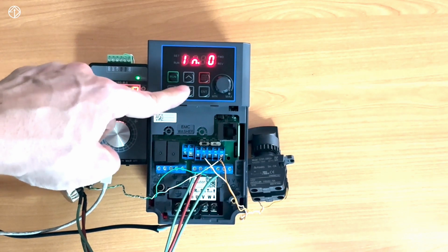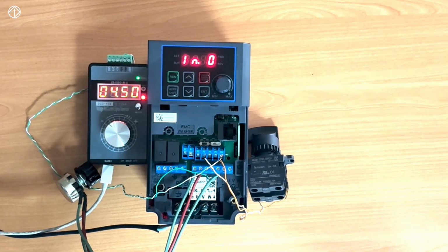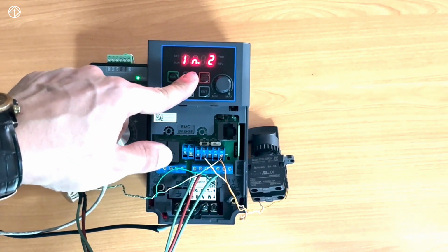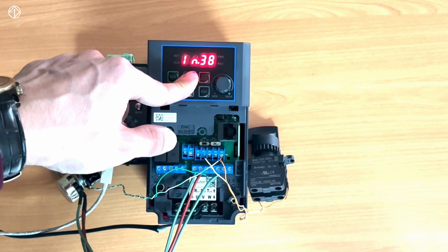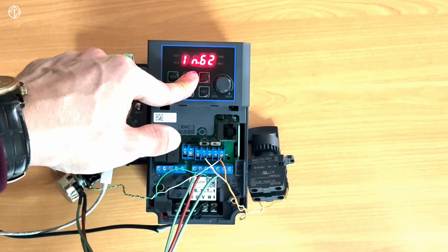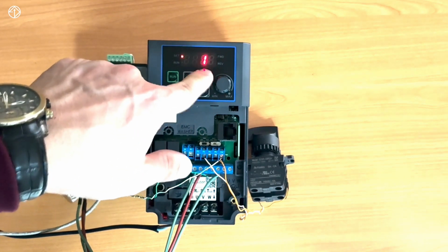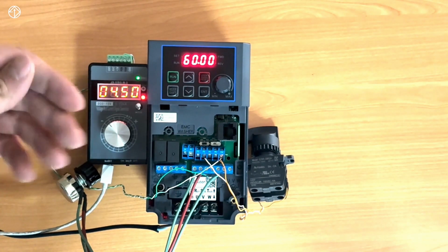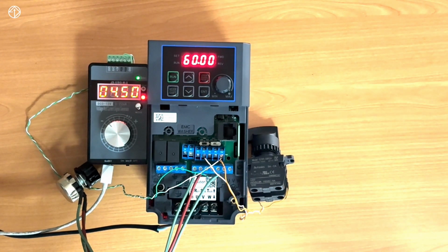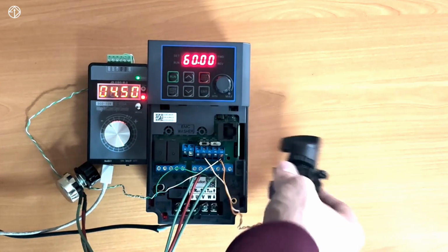For the digital input, as mentioned, we go to the IN group, and whichever digital input we want to use, we set it to value 15. Here I chose P3, which corresponds to IN67. I go into parameter IN67 and set it to value 15. This means that my digital input P3 determines my local remote mode. If it's 0, it's in local mode. If it's 1, it's in remote mode. In local mode, our frequency reference comes from the potentiometer. In remote mode, it comes from the 4 to 20 milliamp input.